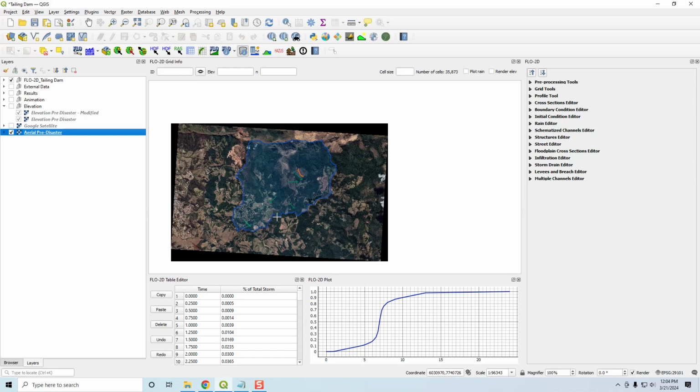And then QGIS has some graphic management tools that can allow you to pin this to the correct location of the map using a couple of points, like a waypoint type thing, and then it will scale it and align it to your map correctly. And also it'll geo-reference it so you can use it in other mapping software.